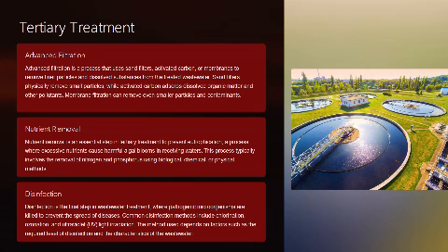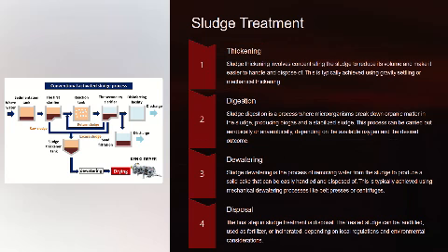Remember I told you about how we are going to kill organisms, right? This is where we kill organisms, and it is a part of the tertiary treatment. You want to remove these organisms because all the other stages that we utilized could not remove these microscopic organisms, because you can't fetch them out with machines because they are very, very tiny. It means you need to kill them. And the way you can kill them is by chlorination, ozonation, or ultraviolet light irradiation, to shine the light on them and kill them and make sure that they are dead and we can have safe water.